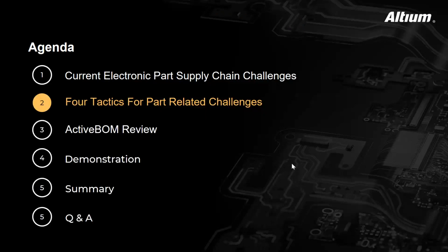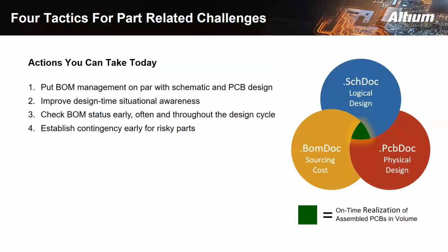And now let us discuss the 4 tactics for part-related challenges. Here are the 4 tactics for part-related challenges. Put BOM management on par with schematic and PCB design. Improve design time awareness. Check BOM status early, often, and throughout the design cycle. Establish consistency early for risk parts.